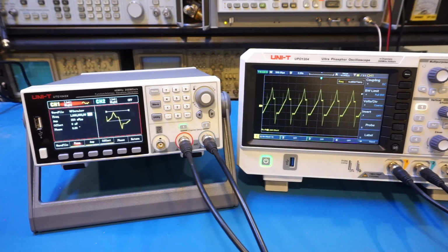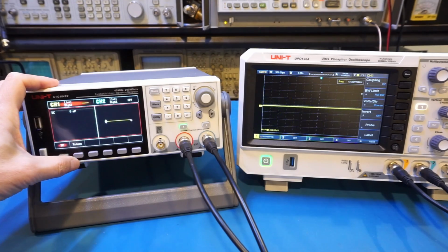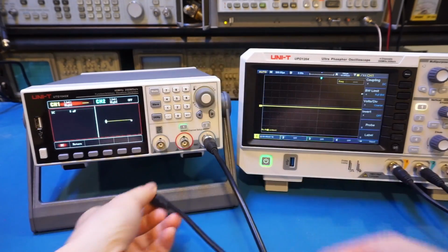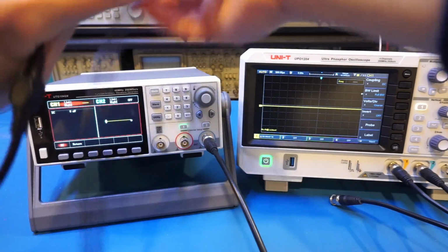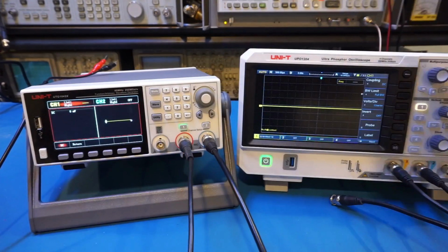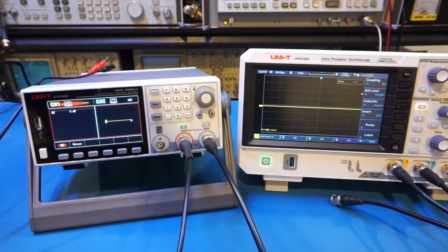And remember, because we have a 16-bit arbitrary waveform generator, I do expect the output voltage setting to be a little bit more accurate on this one compared to the 962E. So let's actually take a look. So let's go back to waveform. Let's go down, and let's output DC. So let's actually measure the output voltage using a multimeter. So I'm putting in a BNC to alligator clips. And I'm going to use my UNI-T UTG1042X Plus to do the measurement here. So all the equipment here is UNI-T.